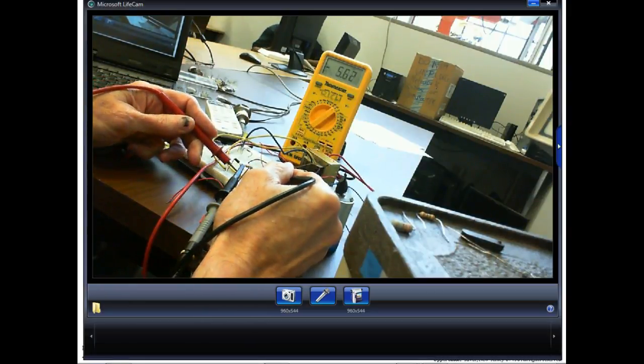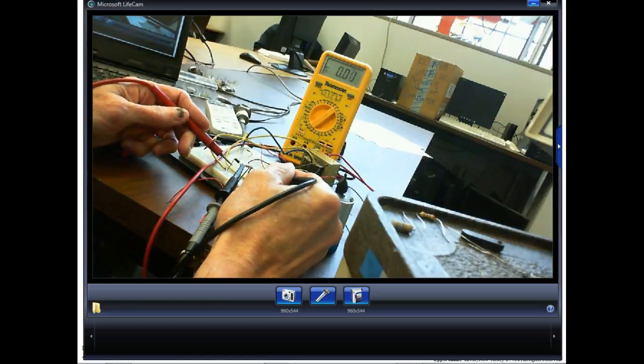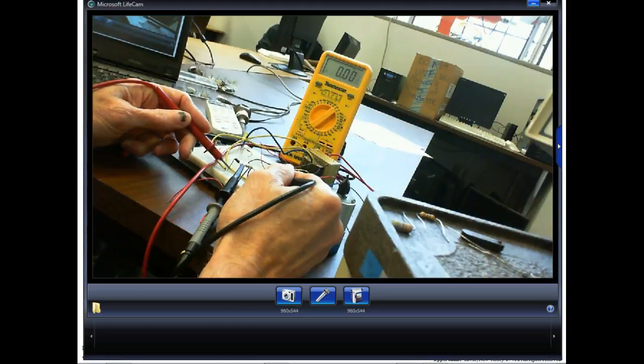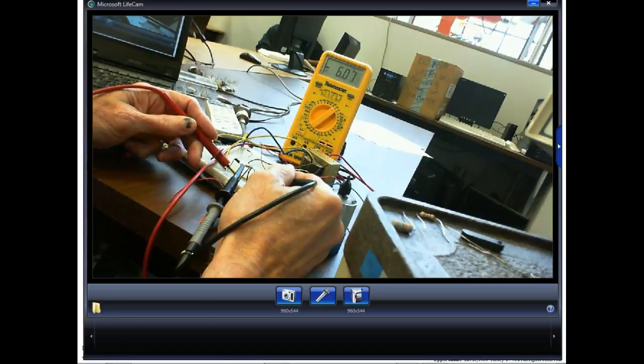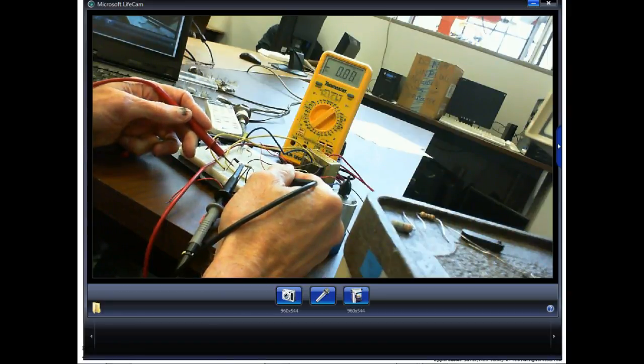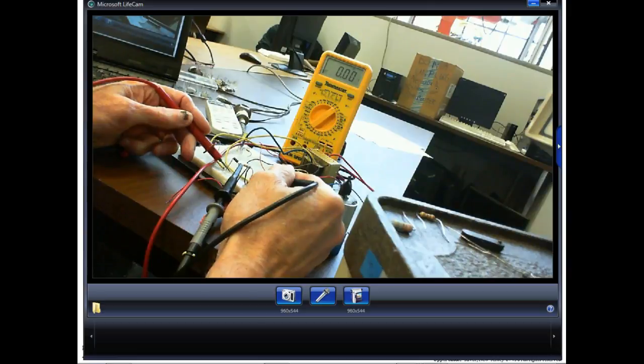So I've got my meter right here. It's measured minus here. I'm going to put it across the transformer, and it measures 0. So how could I have a minus 6.1 volt right here and have 0 volts right there? Because I got my meter on it. I got my meter on DC. And this gets people screwed up too.